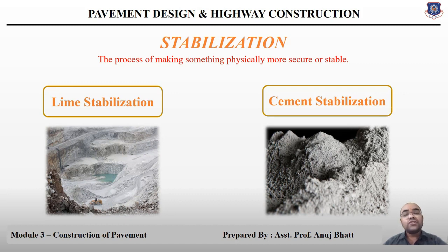Now well graded soil containing gravel, coarse and fine sand will require 5% of cement by weight, and if the material is plastic clay, it will require 14% of cement by weight.